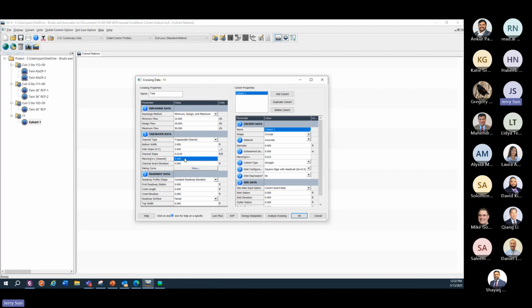If they use 0.03, that's acceptable. If you see a channel Manning's n over 0.05, 0.06, that's not good and really not reasonable. So remember the channel is between 0.03 and 0.05, around 0.04. If you use 0.04 or 0.035 for channels, nobody will doubt you. You're within a good range.